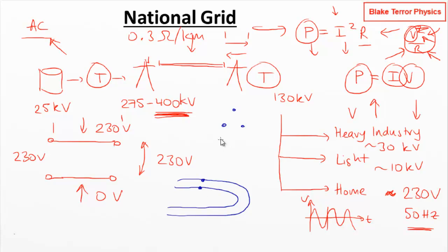But 2 of these pins, the live and the neutral, will tap into these 2 wires, and they'll go off to some device which we've now connected up to our AC supply. So you just have these 2 long cables that run everywhere. The alternative is, for every socket that you want, you run a pair of cables. Our supply comes in here, our 230 volts, you'll have some kind of fuse board, and every time we want to connect a socket somewhere, we'll run cable out from live and neutral to the socket.